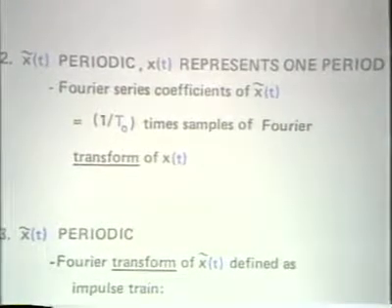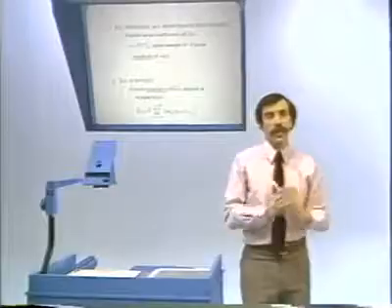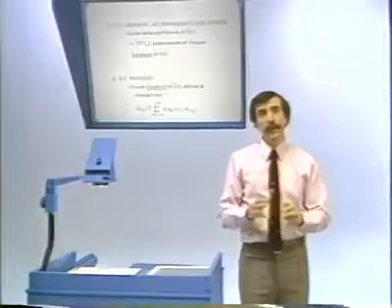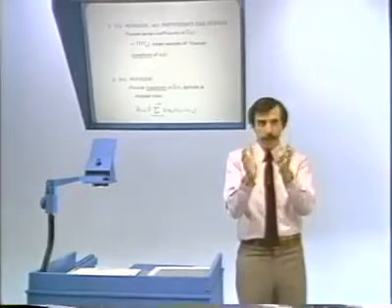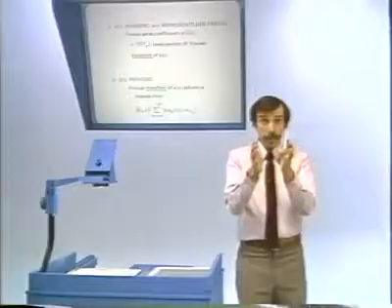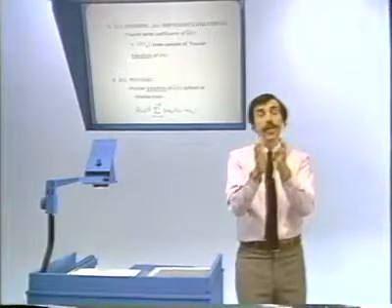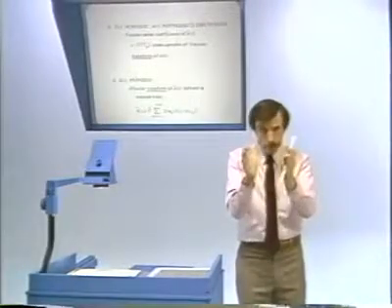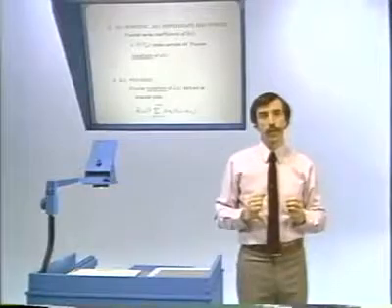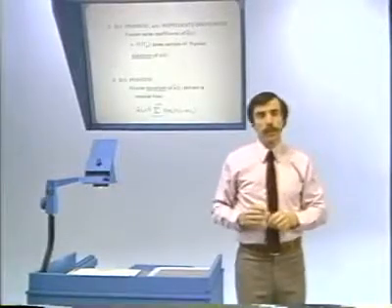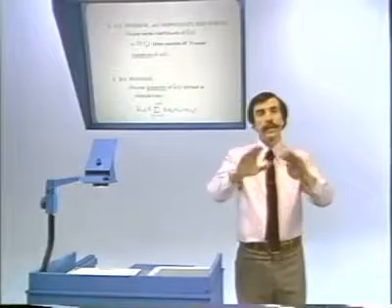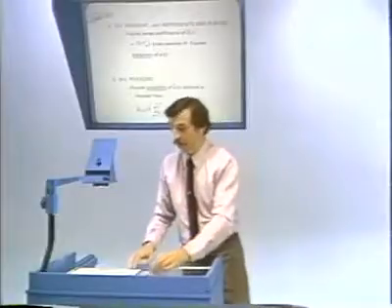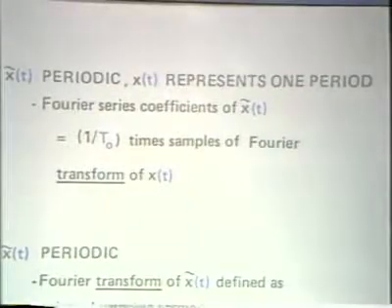That flows easily from all of the things that we've built up so far, because the Fourier transform, essentially by definition of the way we developed it, is what we get as the Fourier series coefficients as we focus on one period and then let the period go off to infinity. The Fourier transform of one period is then the envelope of the Fourier series coefficients. And so in continuous time, we have this relationship.